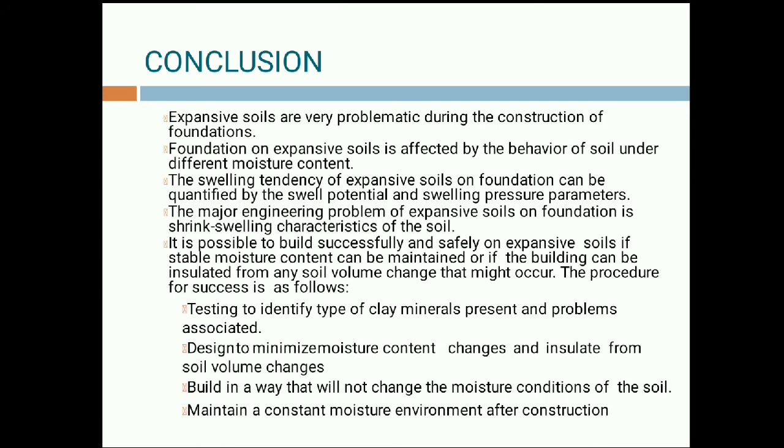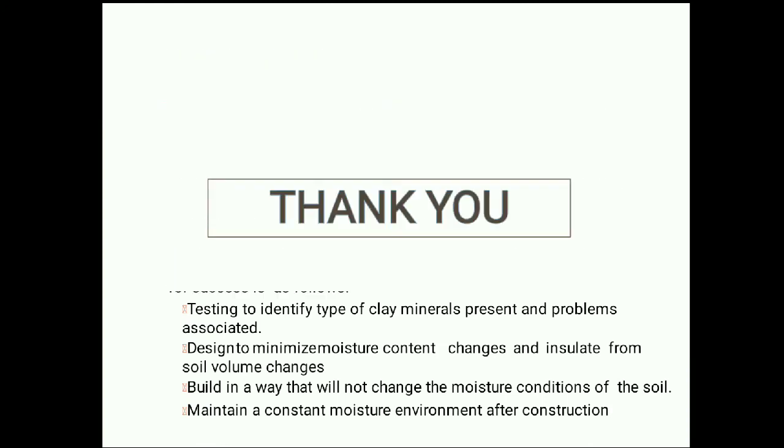The structure should be designed to minimize moisture content changes, in such a way that the amount of moisture variation will be very small, and insulated from soil volume changes. It should be built in a way that will not change the moisture condition of the soil and maintains a constant moisture environment around the building surroundings. Thank you.